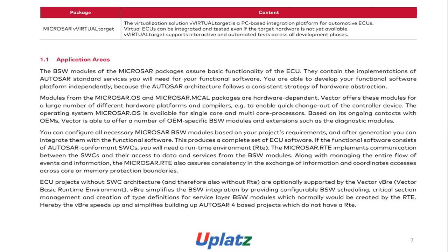The operating system Microsar OS is available for single-core and multi-core processors. Based on its ongoing contact with the OEMs, Vector is able to offer a number of OEM-specific BSW modules and extensions, such as the diagnostic modules. You can configure all necessary Microsar BSW modules based on your project's requirements, and after generation, you can integrate them with the functional software. This produces a complete set of ECU software.